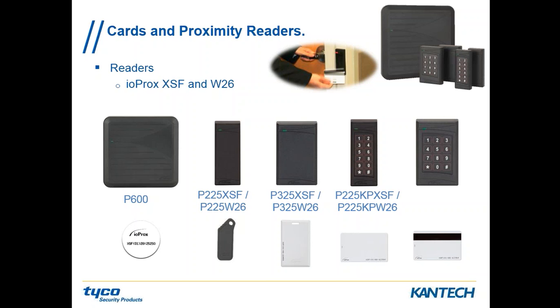That allows us to do an installation at the door where the user might, based on what the customer needs. Of course, we can enable that door for reader card only, or pin only, or reader and card and pin, and we can put them on a timer if we want to. So that can be 24/7, or sometimes, depending on the building, they're telling you, all right, during the business hours, just normal prox, and they can get in. And after business hours, we need the user to use the card and the pin and stuff like that.